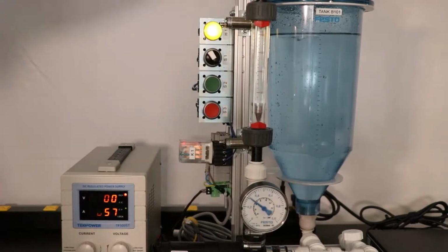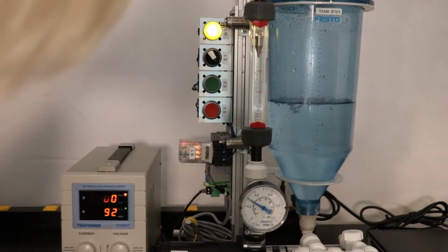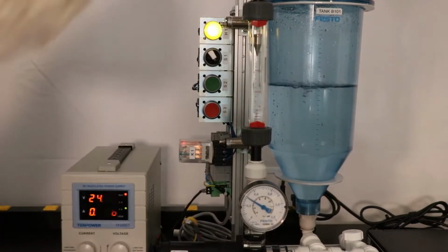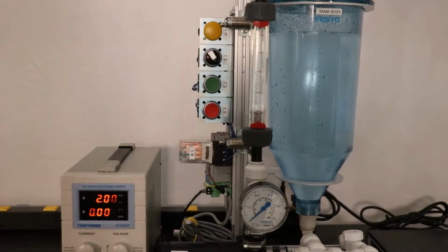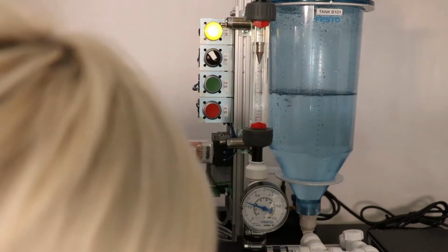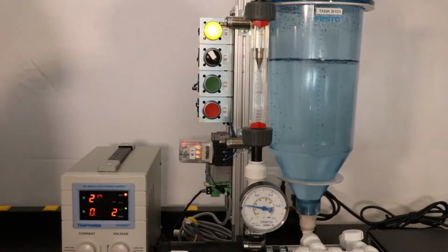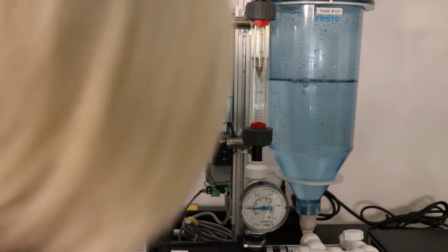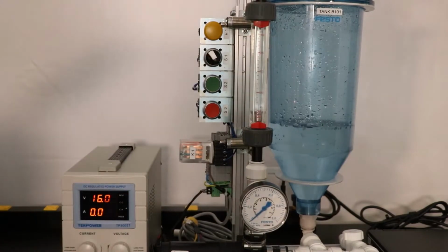In this experiment, we're going to be trying to find the comparison between the supplied electrical power and the received hydraulic power of this pump and of this system. So I'm going to use valve 103 to adjust my flow rate at 24 volts to my maximum of 400 liters per hour. Using voltage as my independent variable, I'll reduce the voltage by 2 volts at each data point, and at each data point I will record the voltage, the current, the pressure, and the flow rate.